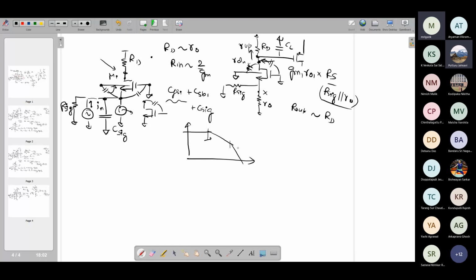And that basically gives you some information about the frequency response or frequency behavior. As I said, the trade-off is very clear in this circuit. The trade-off is between the gain, the swing, the overall bandwidth, and the input impedance. The input impedance comes in as an additional parameter, because for current input I want a good, small input impedance. In common source that was not a concern, but in common gate that is a concern. So along with gain, bandwidth, and swing, we have another parameter now, the input impedance, and you need to meet requirements for all these four. This is clear? Any question before we proceed further?